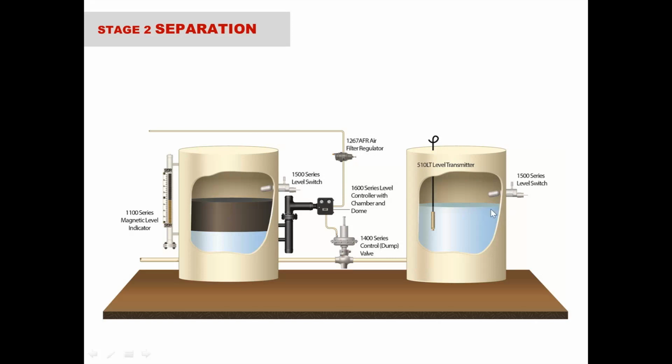And so really the main reason that you'd want multiple stages of separation is for stability in your process. If you try to do too large of a pressure decrease at once within the production process, you could get flash vaporization, which could cause instability in the product, and then also some safety concerns. So really that's the main reason to do multiple stages of separation.